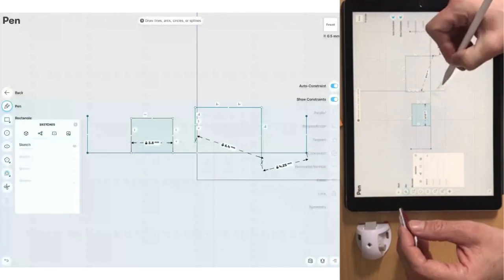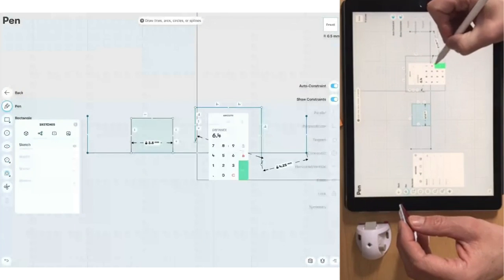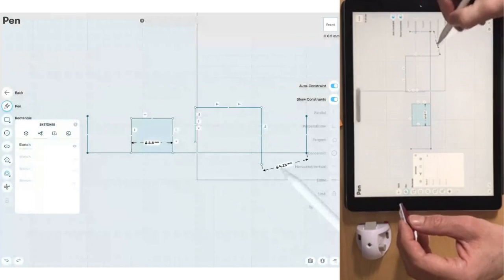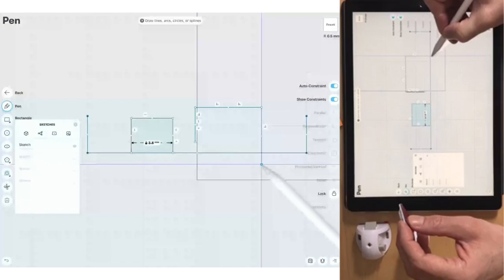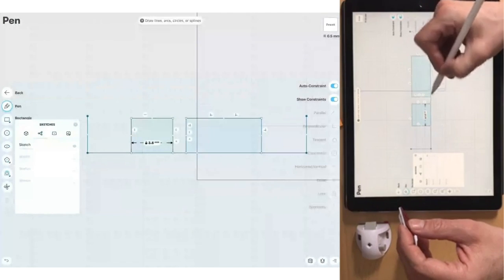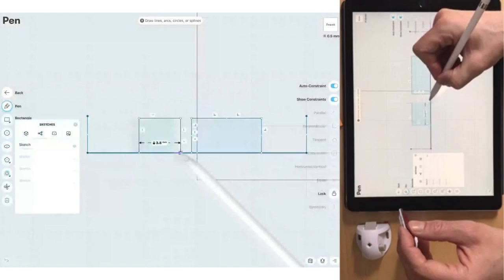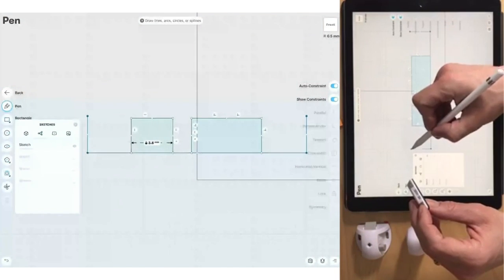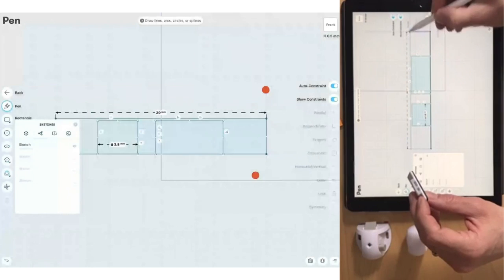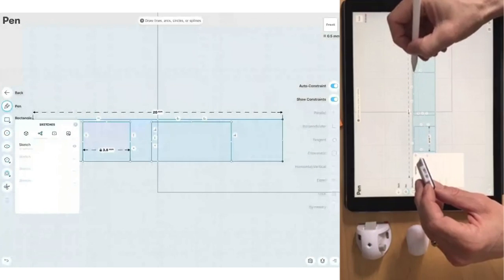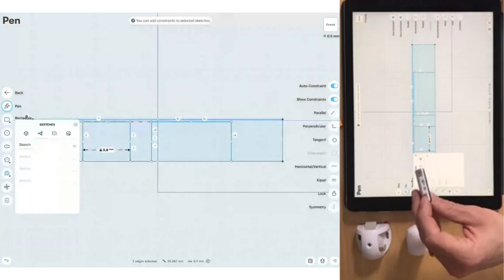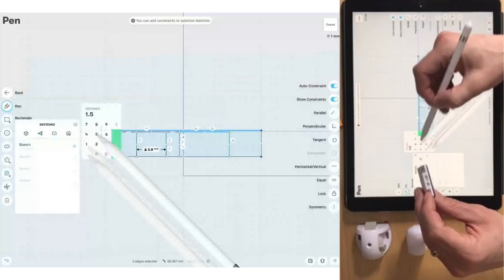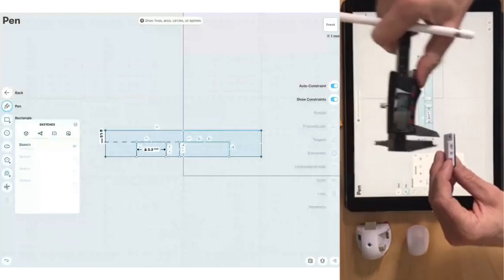Okay, if something like this happens, you see that the lines move a little bit crazy, no? Then to fix this, because Shaper uses a sketch solver, and I made the mistake of not making sure that these lines are correct, we simply remove the dimension and add them afterwards. So we said this is 1.5. Very good.